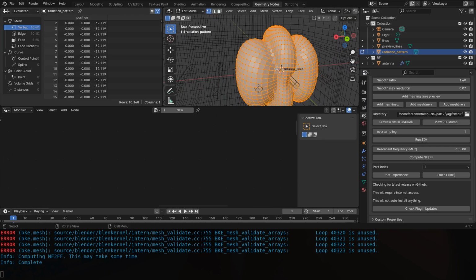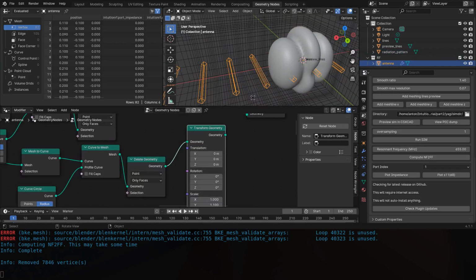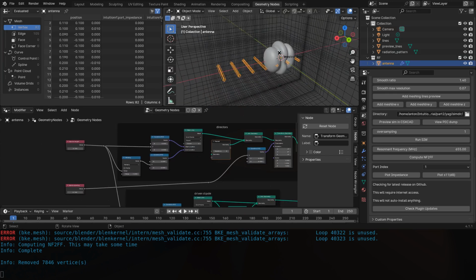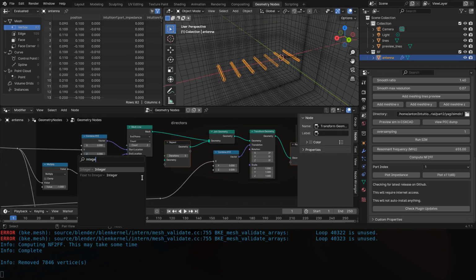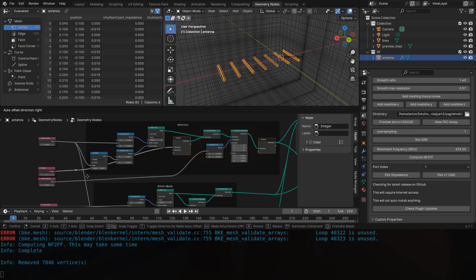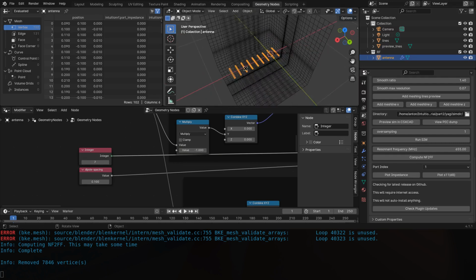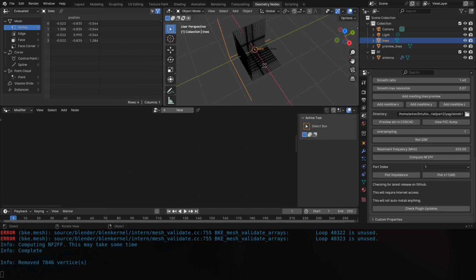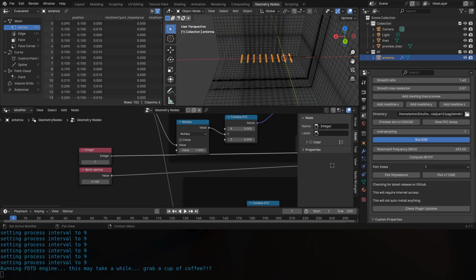Okay, so obviously this is not a very good antenna, and you'd want to optimize this. And let's see what it does when we change parameters. So let's say we can increase the number of directors to make it more directional. Let's try this. We're actually going to make this an integer as well, like this. So this is now a parameter of the system, and we go from 5 to, let's say, 6 or 7. Maybe I need to increase the simulation size a little bit, like this. Okay, run the simulation again.